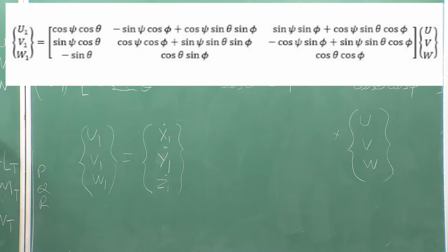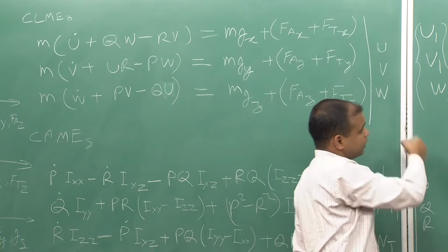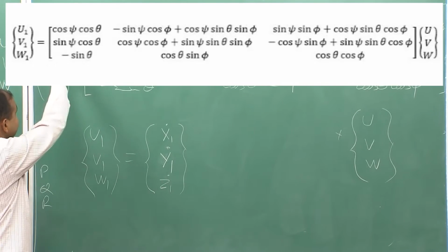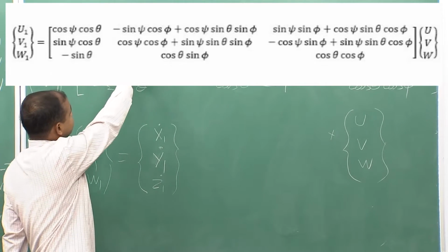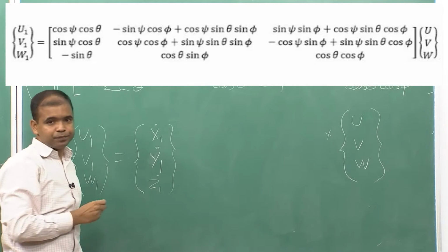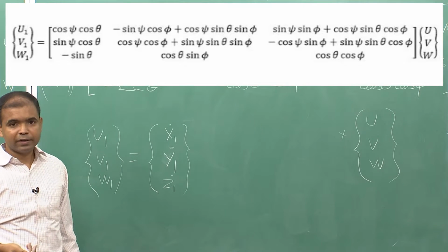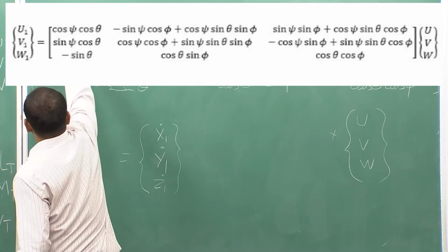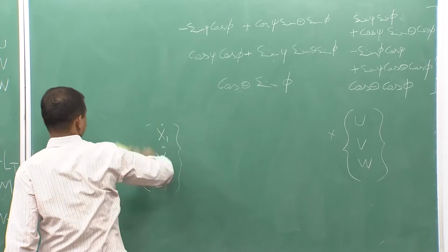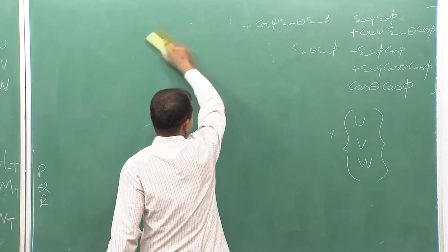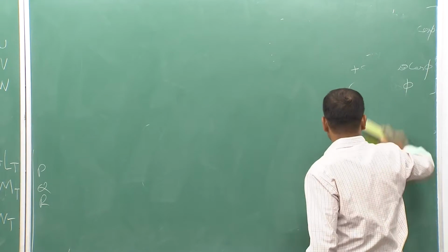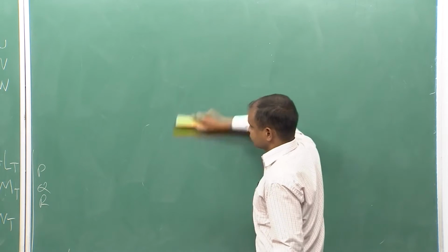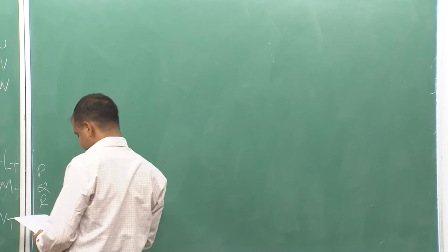From these three sets of equations, we already have the UVW, but to find the U1, V1, W1, we require psi, theta and phi also, and from where we will find this? So, to get this, we will do a small manipulation. The matrix that we had derived to convert the body frame into inertial frame or inertial frame to the body frame, we call the flight path equations.